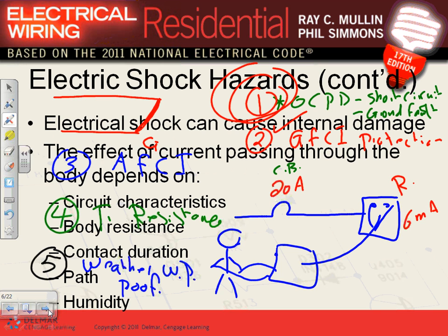Arc fault circuit interrupter, almost in every location that doesn't have GFCI, you need an arc fault circuit interrupter. In residential, tamper resistance is a must. Weatherproof should be in wet location, only wet. If you have wet location, you need to have a tamper resistant, weatherproof receptacle.